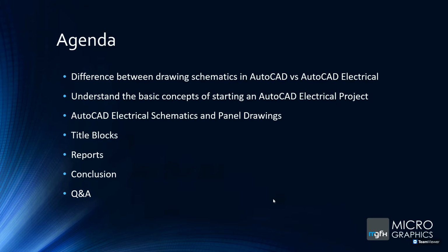Title blocks, this is quite important because the title blocks on a drawing convey a certain amount of information to the person reading the drawing. Things like descriptions or location, where you need to know, what is this drawing about? The information in this drawing is pertinent to where I'm actually standing. So maybe you look at the drawing and don't understand why this is going here. Look at your title block, and you can see the information of why it's going there.